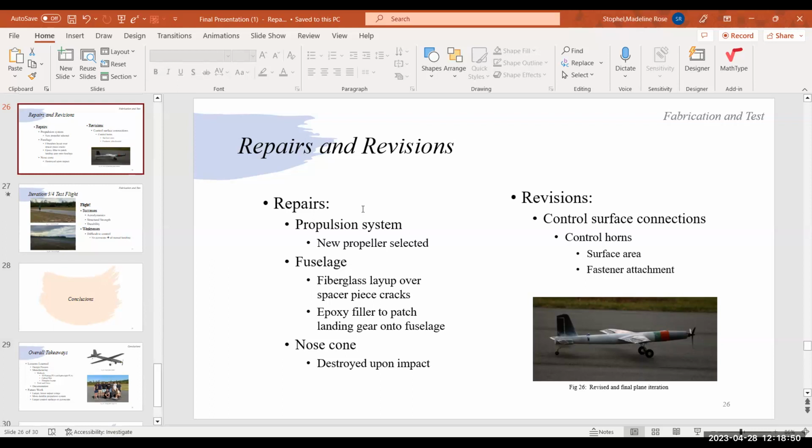How did you size your battery? Battery sizing was determined based on the motor we had selected, and then running at approximately 75% power for the maximum flight window required. Okay. Did you have any concerns about the motor or battery overheating? We did not design for those concerns, and we didn't run into them during our flights, but that is something we would like to address if we were to design again.